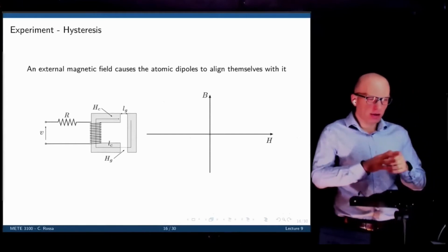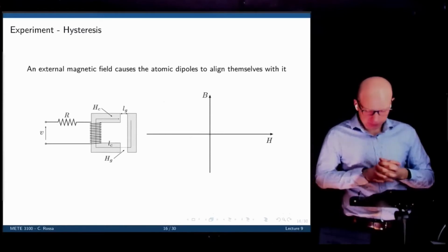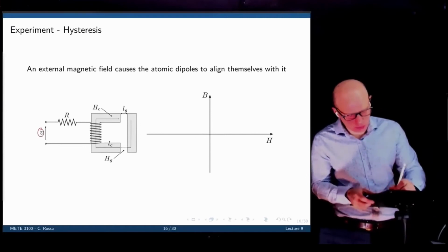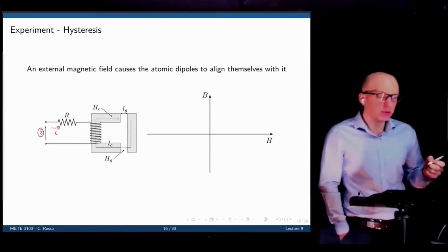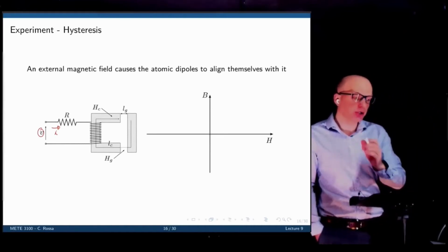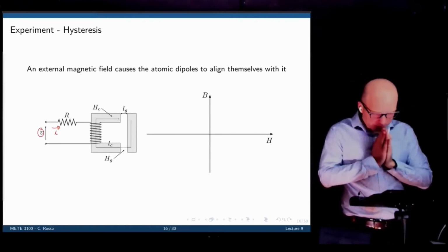If we have, let's say, this actuator like that, we can apply a voltage to the solenoid. The voltage creates a current. The current creates a magnetic field. The magnetic field now creates a mechanical force that eventually attracts the plate towards the core, and they touch each other.